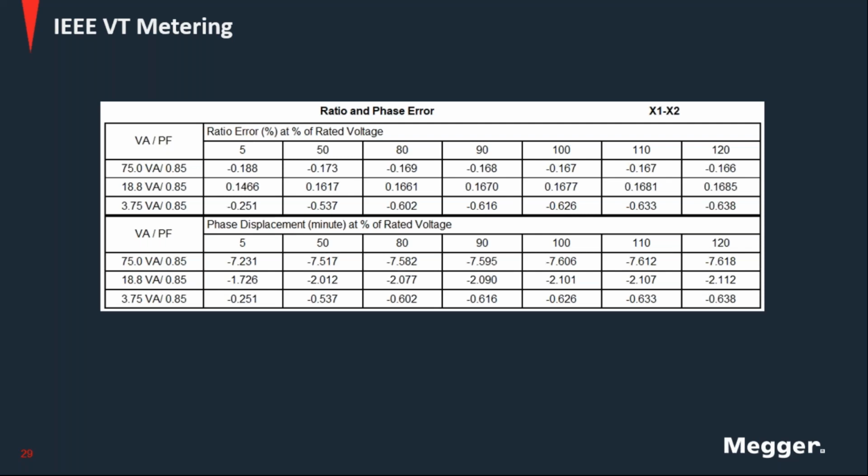In this case, whoever ran this test did not measure the impedance of the circuit connected to the CT. So we don't have the actual evaluation at real conditions, at real burden, but still you can see how linear the behavior is throughout the range of the instrument transformer.